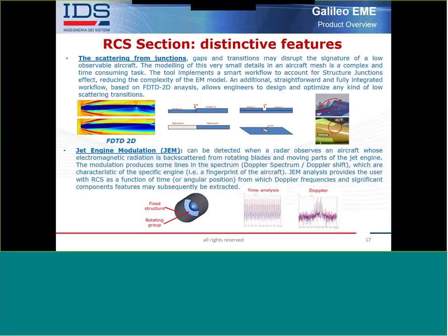These gaps can be a canonical shaped gap, or it could be also some custom shaped gap. And in this case, we can compute the behavior of this gap carrying out a two-dimensional FDTD simulation.